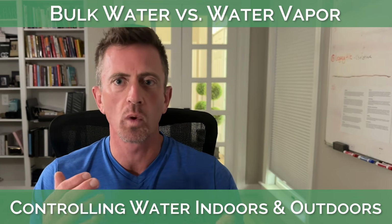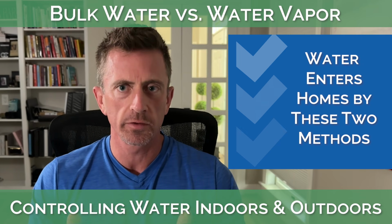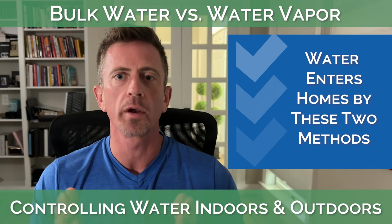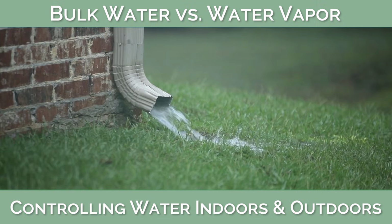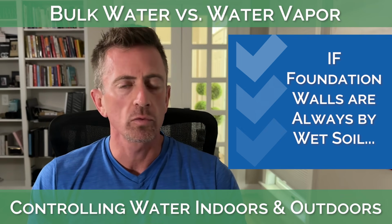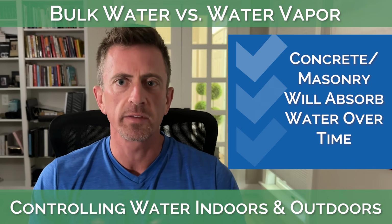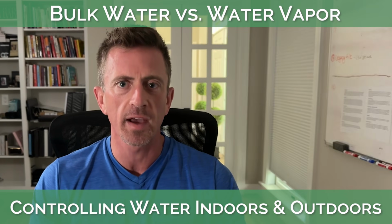Bulk water versus water vapor. The two primary methods water enters your home are by bulk water and water vapor. Bulk water is essentially rainwater that accumulates around the perimeter of your house, and if you don't have proper grading where the ground slopes away from your house, then it's more likely that the rainwater will drain into the ground surrounding your house. If your foundation walls are regularly in direct contact with wet soil, the concrete or masonry materials will absorb that moisture over time.